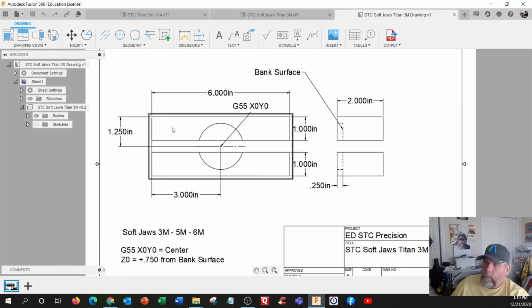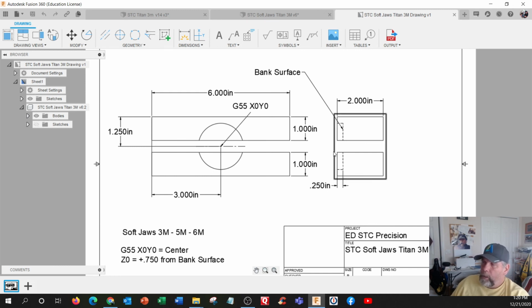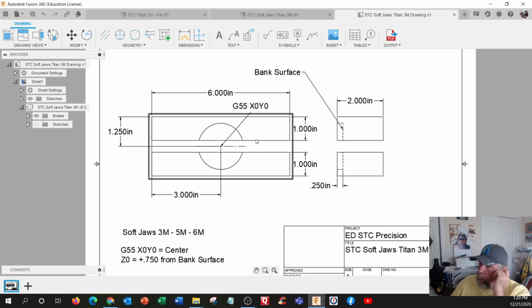And we actually have a milled hole here, and we engraved how to get from the hole to the center of this. Because you really can't probe this. This is a movable jaw. You can't probe the inside of this. But this is also to remake these jaws. We would use the 1x2 inch material. We put in the bolt pattern for the Kurt vise. And we put in a spacer here that would be 1/2 inch wide. And then we machine the middle and take the spacer away. Okay, so that applies to soft jaws in general. Talk to you later.